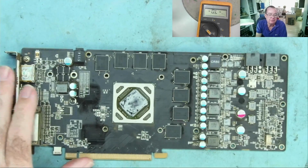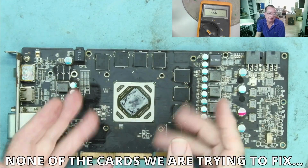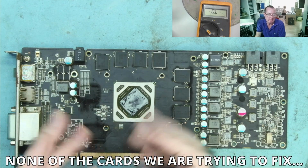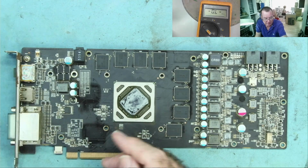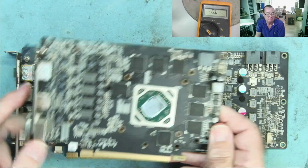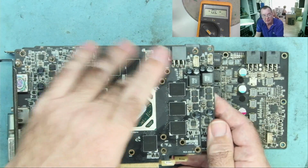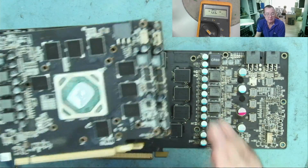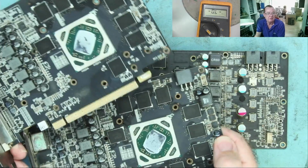So what have we learned? Well, we know none of the cards have a short circuit on the GPU or on the RAM or any of the other power rails. We know there's no shorts there. We know the smaller cards, these RX cards, looks like the RAM has been working very hard because of this oily kind of loop. Probably mining cards. And we also know that the resistances to the GPU are different between these two, okay?